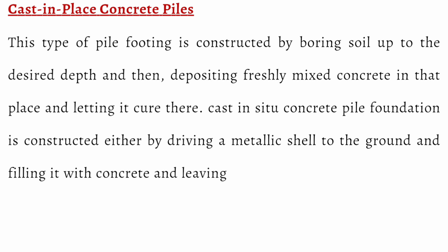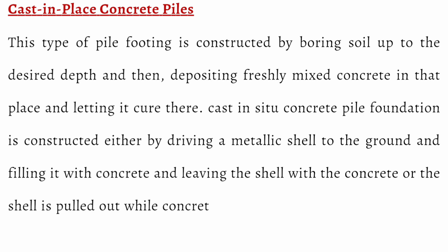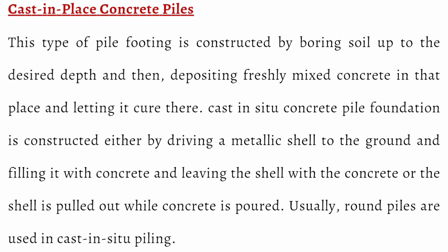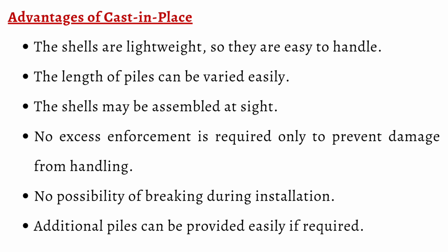Disadvantages of precast piles. Once the length of the pile is decided, it is difficult to increase or decrease the length of the pile afterward. They are difficult to mobilize and need heavy and expensive equipment to drive. As they are not available for ready-made purchase, it can cause a delay in the project. There is a possibility of breakage or damage during the handling and driving of piles.